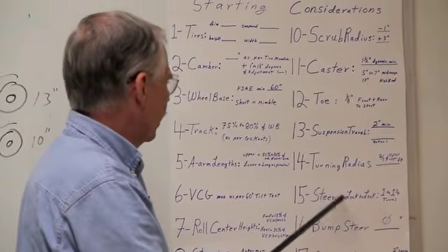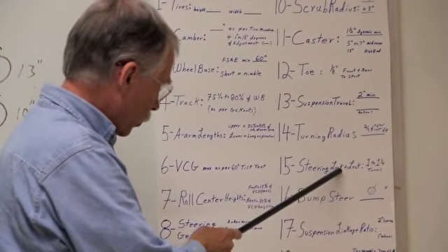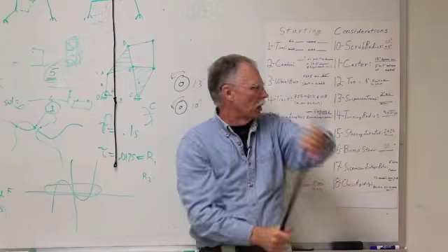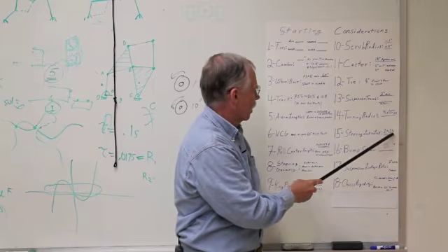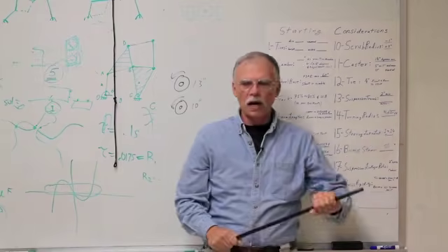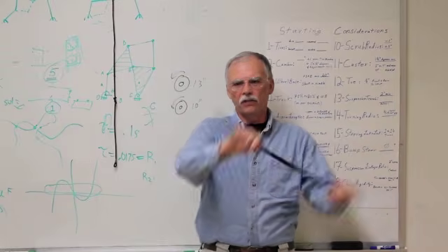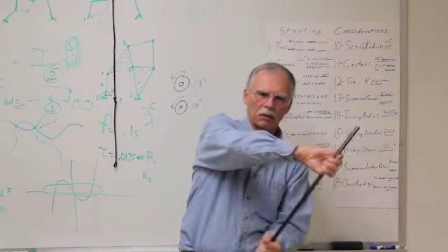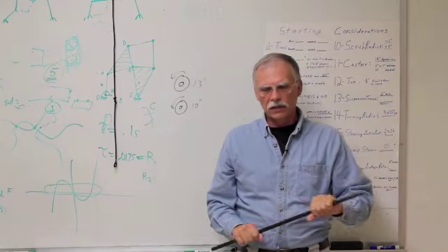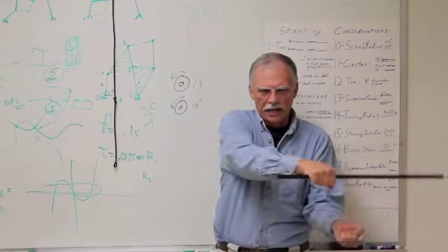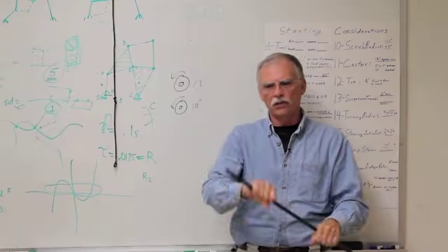Okay, steering motion, lock to lock. Steering wheel, all the way this way, all the way this way. Don't have more than a 1 1/4 turns. Not for autocross, 1 to 1 1/4. Why? Because if the driver is having to shuffle the wheel around, he's going to have slower lap times, period. He needs to be able to. Autocross, especially on these cars, is absolutely thrust, cut, push, slam, jam. It's slam and jam. There's no real finesse to it. Okay.